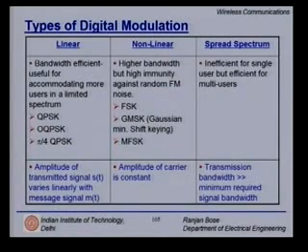In this slide, we will look at briefly the different types of digital modulations. You can classify them into linear, non-linear and spread spectrum techniques. In linear modulation techniques, which we will discuss today in detail, they are bandwidth efficient, useful for accommodating more users in a limited spectrum. How do we choose one modulation scheme over others? We will discuss that in one of the subsequent slides.